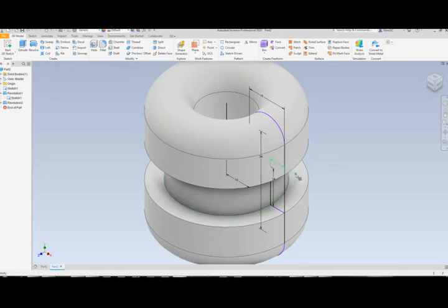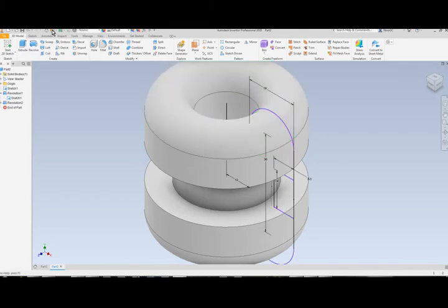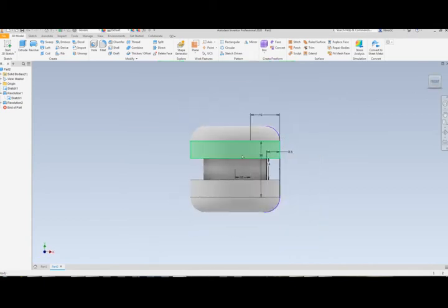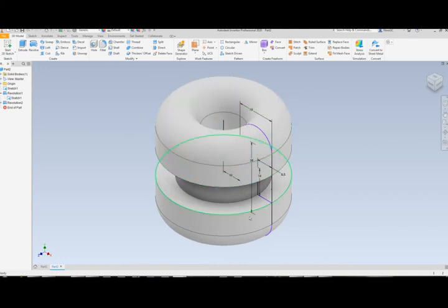Let's make another change. Let's make the opening of the rectangle a little bit bigger. So we'll make it, say, 8.5. There we go. Once again, local update. Let's make the overall slot itself, let us make it, say, 19. There's 19. Local update. Now it adjusts. So the part itself is fully controlled primarily through the fact that if we control the sketch, we actually are controlling the part.